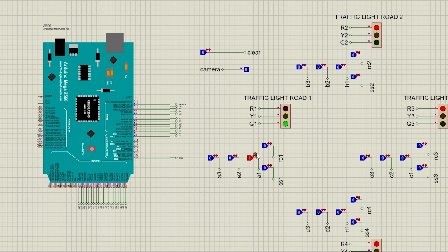As soon as the car passes, this sensor will no longer read the car, and this will become 0 again. Once it becomes 0, we can see after it goes through a transition yellow phase, the signal will become red once again. Now suppose we have a car in B, and so this signal of road 2 becomes green. Now before this car can pass,